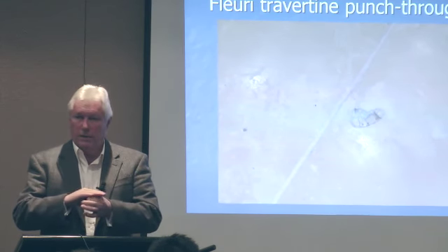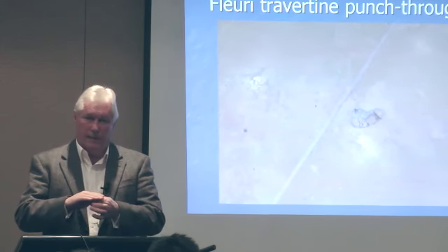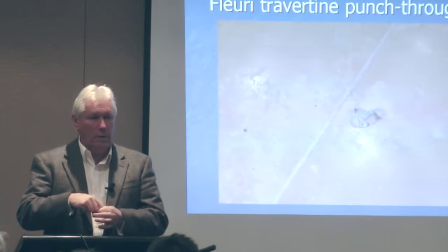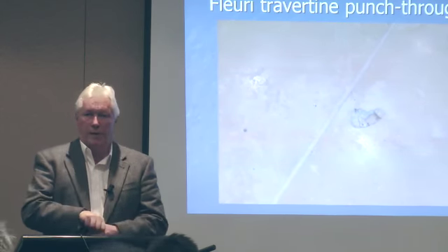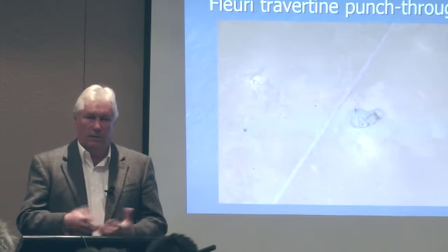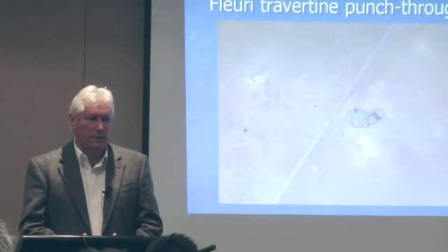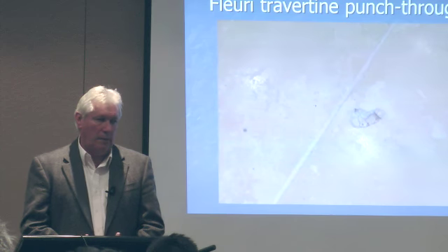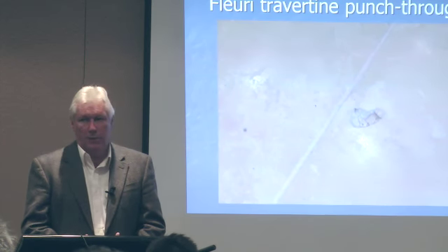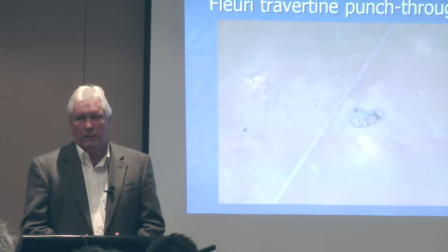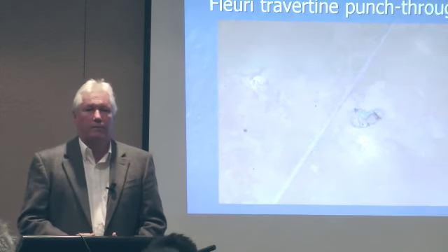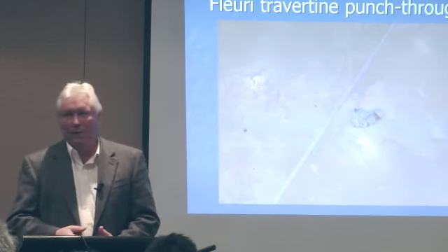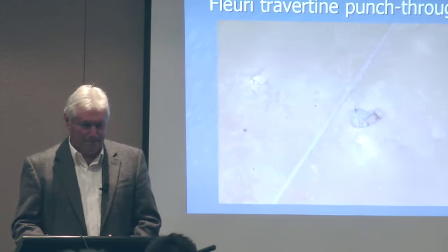So we end up with flower cut, which doesn't give us as many holes, but it can give us the hole that's just underneath a very thin layer of stone. So somebody walking on it, particularly with high heels or the like, can get to that point and punch it through. Not a big problem. It's got to be fixed. Put in some coloured fill, and we're usually out of there. But some stones are really bad with it, and once again, it's knowing the problems of the stone and the supplier. If it was really cheap, you might find out why it was cheap.